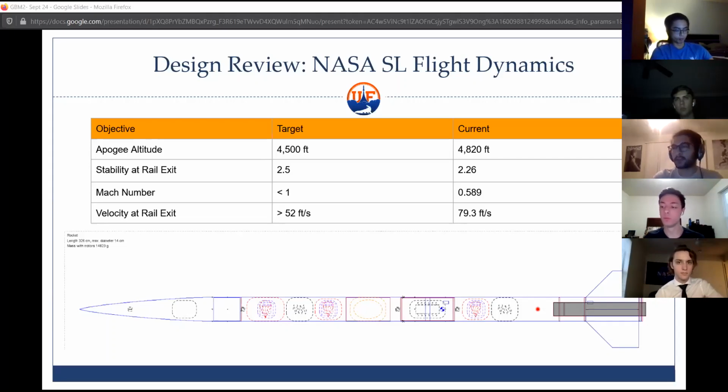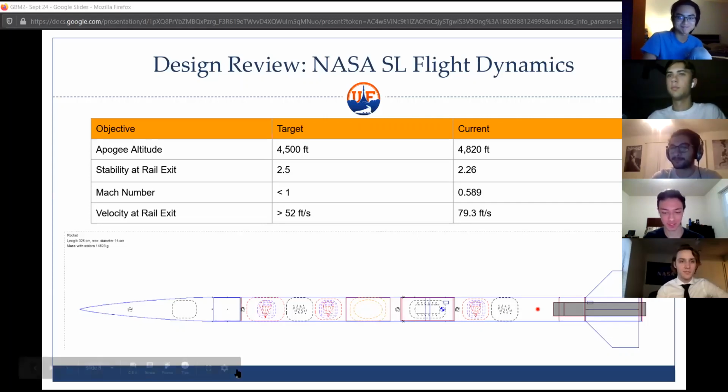Yeah, I'd just say make sure that the parachutes, the ejections, and the payloads can all fit in that forward fuselage. Because if anything, you can always make the aft fuselage smaller and the forward larger to make more space and just account for it. But just something to know. That was an issue last year because during manufacturing, I made an error and accidentally made our forward airframe like 2 inches too small. So if that doesn't happen again, planning should help mitigate that error.